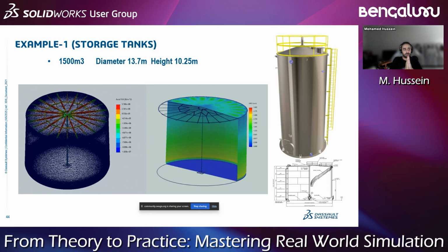First of all, you are not able to perform a simulation if you have parts that are interfering together. You have interference detection mode in SolidWorks in parts and simulations, and you can check if there is any kind of interference, and you are not able to perform your simulation if there is. Okay, so this is the first one.